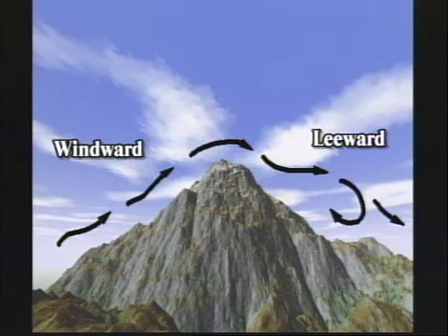Give special attention to wind direction and velocity. If you approach from the lee side, do it with caution. Typically, downdrafts and turbulence will make it difficult, if not impossible, to climb up to the pinnacle landing area. The updrafts on the windward side, on the other hand, can be beneficial in carrying the aircraft up to the pinnacle. If you must climb to a pinnacle or ridgeline, do it on the upwind side for this reason.